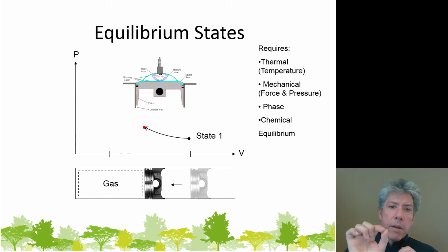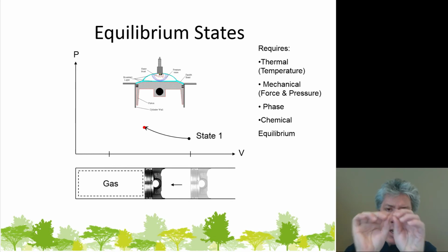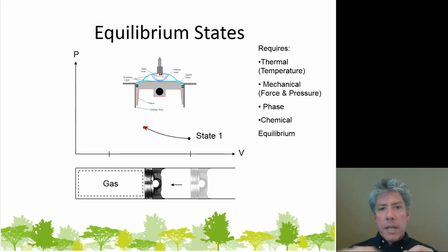But what really happens when the burning of the fuel begins is the spark plug lights up the fuel in one area, right? It's just a small spark in one area of the cylinder. And so the air-fuel mixture starts to burn from that point outward, okay? You can kind of see the pressure wave and the flame front advancing. The pressure behind that pressure wave near the spark plug all of a sudden spikes, right? It goes up really fast because the temperature of the gases in that region is rapidly going up.